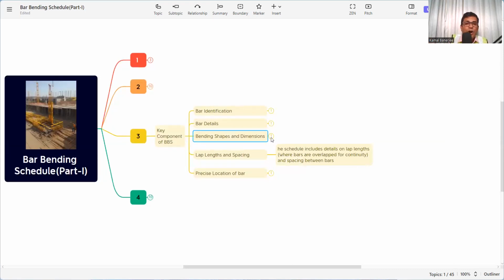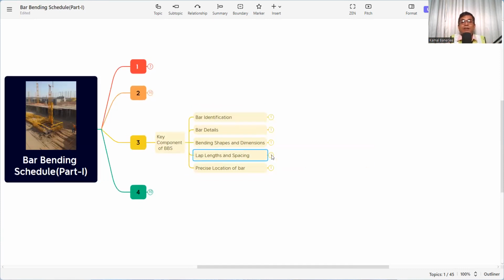So that is not acceptable as per the design criteria. According to the splice zone, we need to splice, and that splice detail also has to be provided in the bar bending schedule, so that whenever we are working or checking, we can find out this is the splice zone, here there is a splice of the bar, and the precise location of the bar.